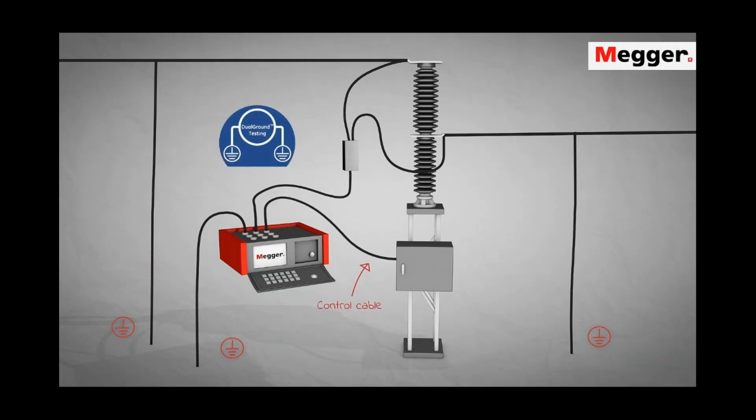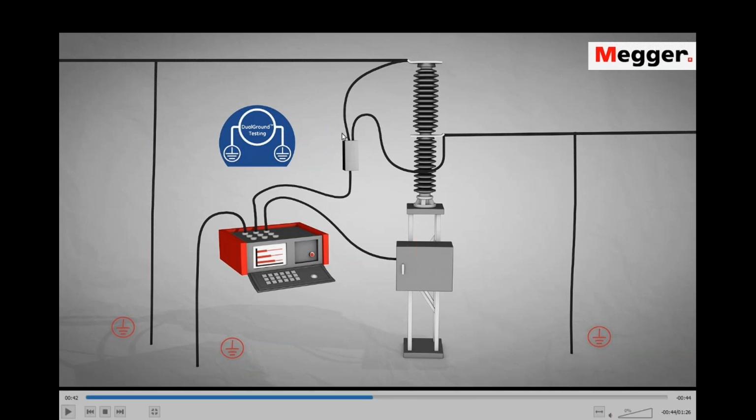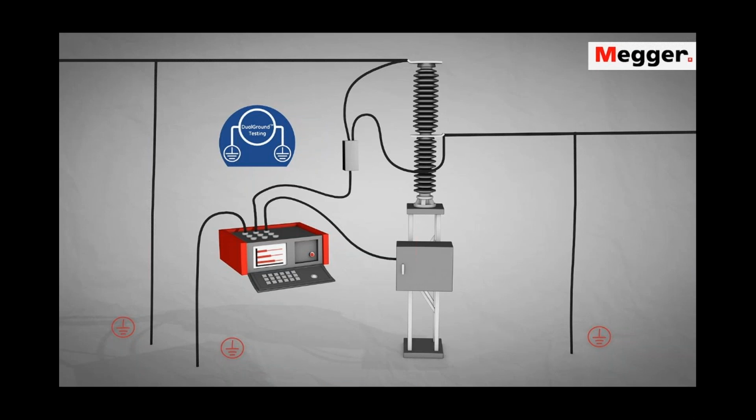You need to connect your control cables as you would do for a standard timing test, and perform a measurement, with the exception of the DCM module, which is the high frequency part of the system. The rest of the connections and the rest of the analysis is done exactly like a standard timing measurement. So once you learn how to use the instrument, let's say for a standard timing measurement, it becomes very easy to use the DCM method to do a dual ground test.